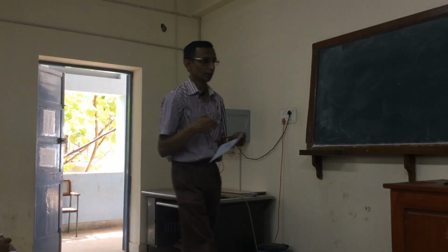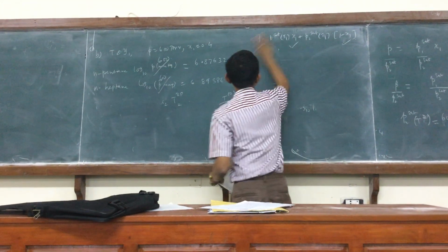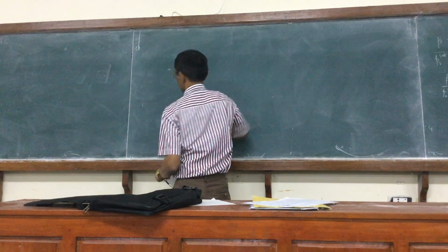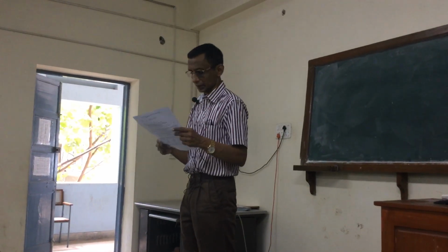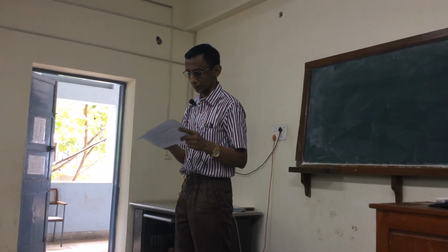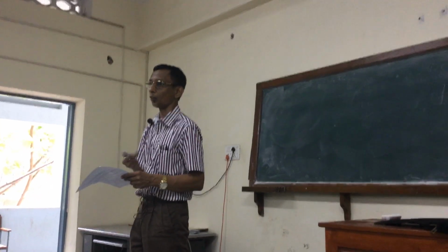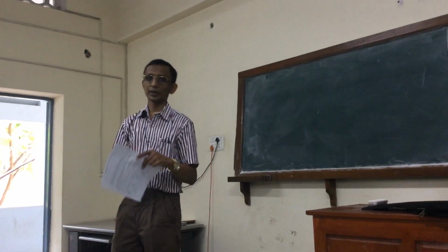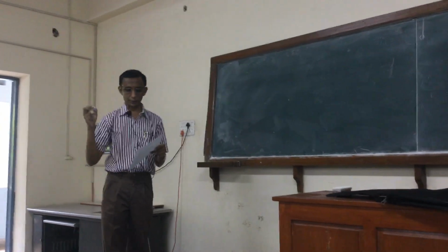Basically, a certain fitting is done to calculate the parameters from the VLE data, and then you use the parameters to extrapolate and get the VLE calculations done outside the range for which data is not available. Here, what I'm going to do is consider a simple procedure. We're just using the fact that the system has an azeotrope, because this data is very well known. So it simplifies the calculation of the parameters. Otherwise, you have to do some curve fitting. We'll see how to do it in the simplest case, where we're just using data at one point to calculate the parameters.